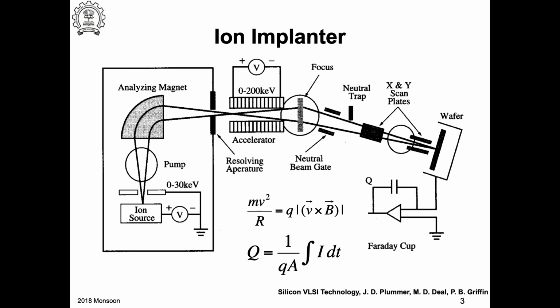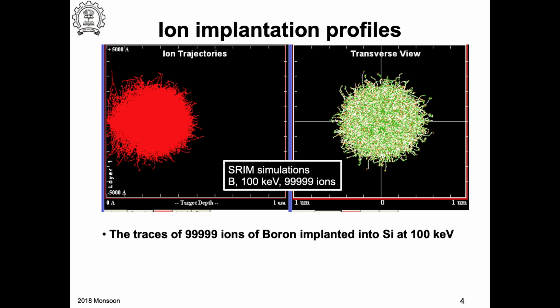Meaning, the channel region, let's say the depletion region is half a micron. To make it simpler, we'll assume this is 1 micron. So you're talking about a cubic micron, right? So this would be how many cubic centimeter? 10 raised to minus 12. A cubic micron is nothing but 10 raised to minus 12 centimeter cube. But then suppose the doping here is 10 raised to 17 per centimeter cube. How many dopant atoms will be in the device depletion region? Just multiply, right? So 10 raised to 5. Fairly large.